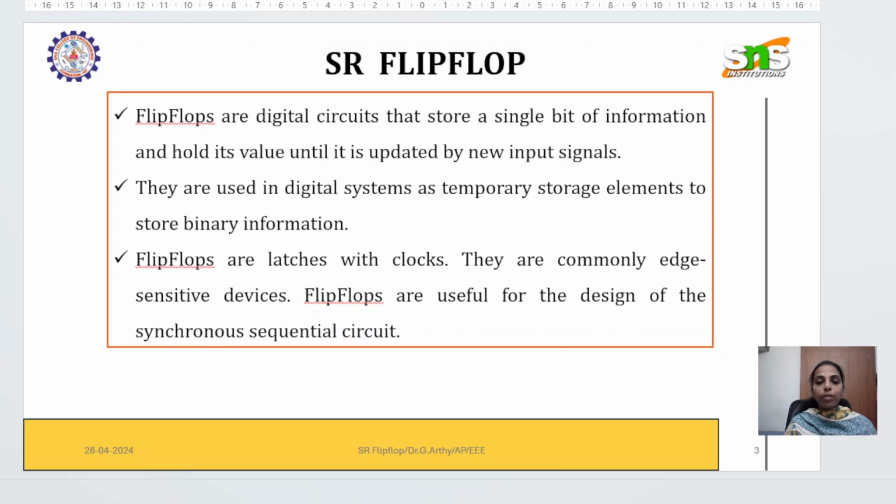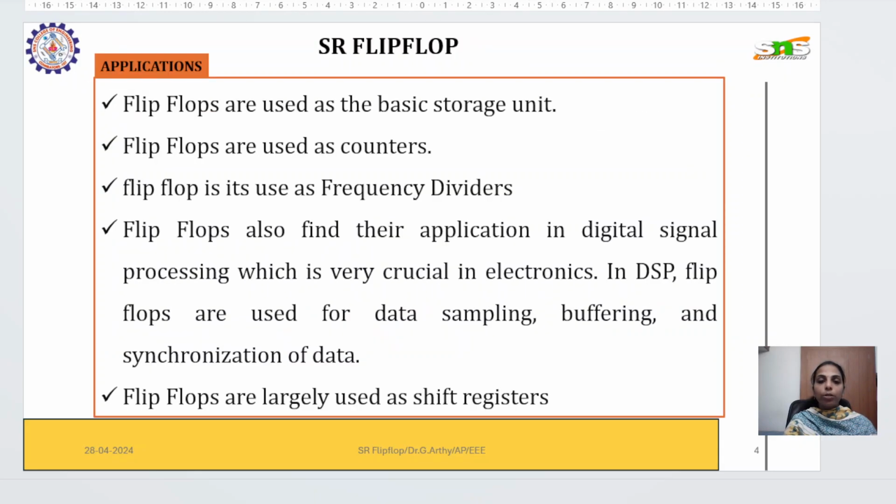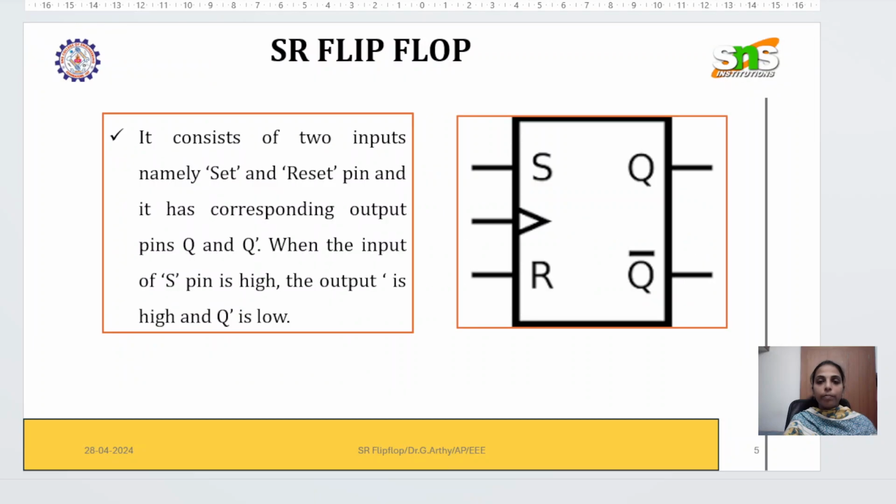Flip-flops are useful for the design of synchronous sequential circuits. And do you know why these flip-flops are being used? They are used basically as storage elements. They are used in counters, frequency dividers, and many other DSP, digital signal processing circuits for data sampling, buffering, and synchronization of data. They are also used in shift registers. So all these applications are common for most flip-flops.